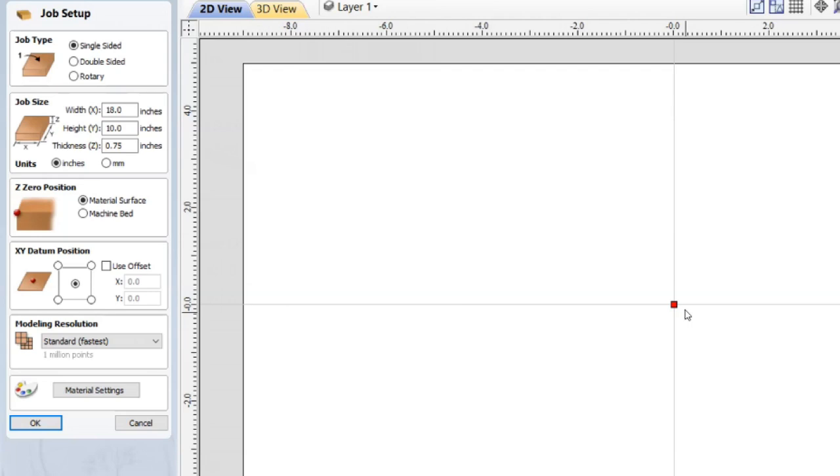And if you created the tool path that's going to carve your project, then you would have to set your 0 point off the middle of the project. It's just easier to design off the middle of the project. Sometimes you'll want to go at the bottom, sometimes you'll go in the middle, but later on you change it to a corner.